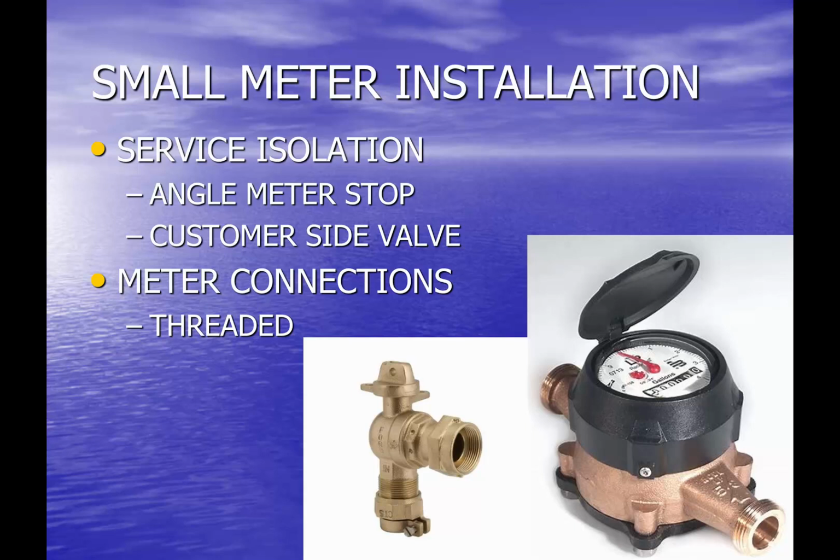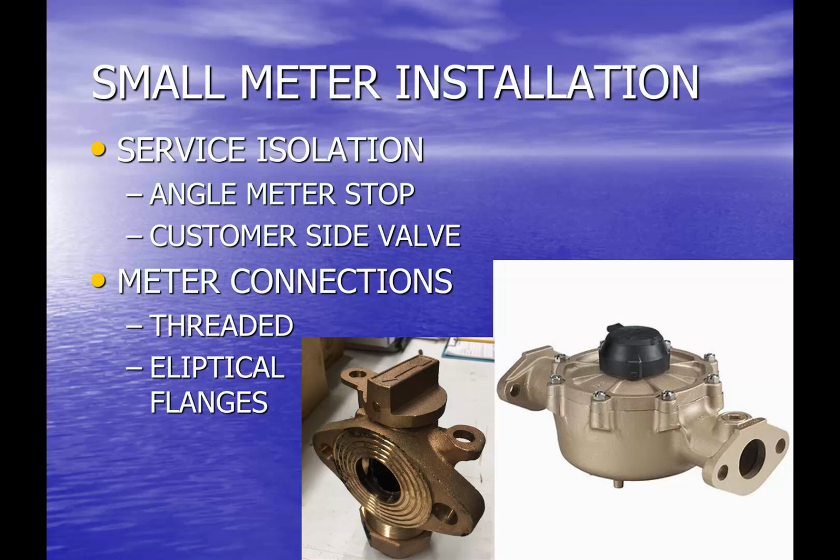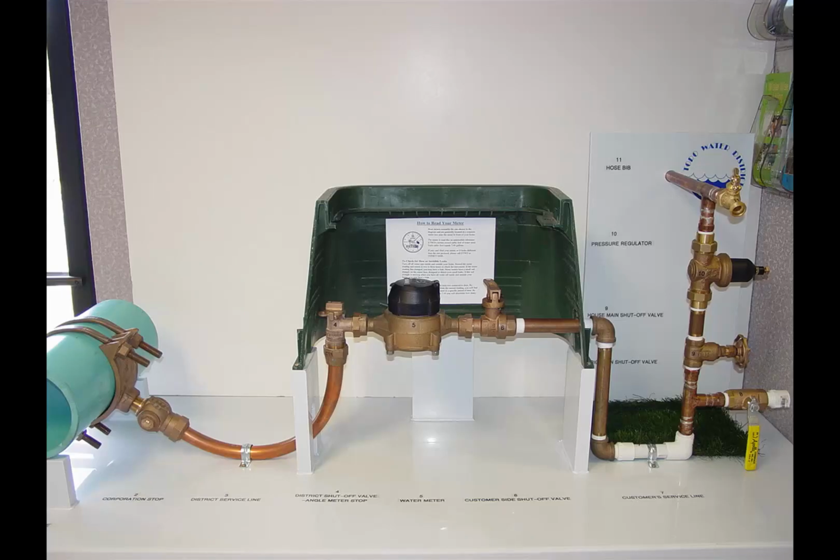As you get to 1.5 and 2-inch, we've touched on the word elliptical flange before. That's what the elliptical flange looks like on the meter side, and then a picture of an angle meter stop with an elliptical flange. So they get bolted. It's obviously a 2-bolt connection with a gasket in between, and that's how you connect the larger meters to the angle meter stop, and ultimately to the customer side valve as well.